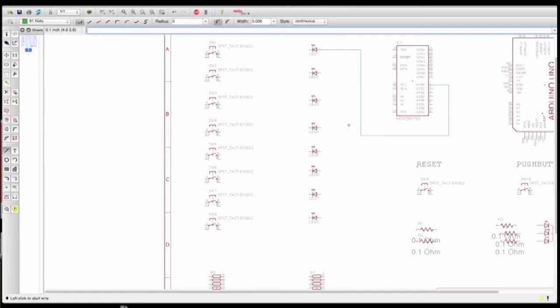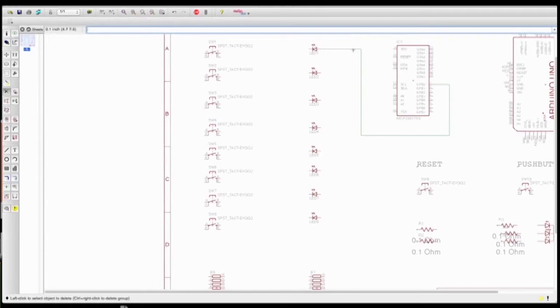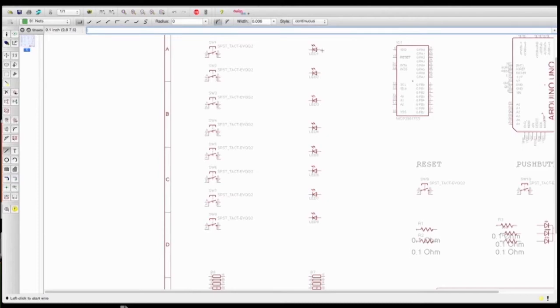What you'd have in the very end is what we have in Fritzing, which is wires running everywhere. It makes it confusing. This is where Eagle has something that is awesome. So I'm going to delete my runs so we don't have this. And I'm going to add a small wire to this side of the LED, just like this, and one on this side. And then I'm going to add a small wire right here, just like that. And you can now name these, and they basically make a bus.